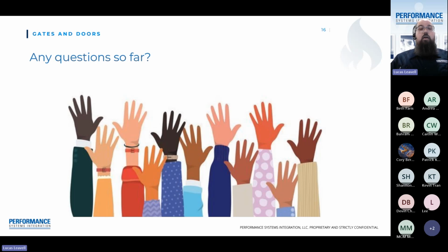I would like to call out a question that I received a few weeks ago. This customer has a garbage chute, but there's no door at the bottom. It's just a hole in the ceiling of their garbage room that drops into a dumpster. There was never a door there. Should they have a door put there? The short and sweet answer is yes, because now that chute is a chimney.